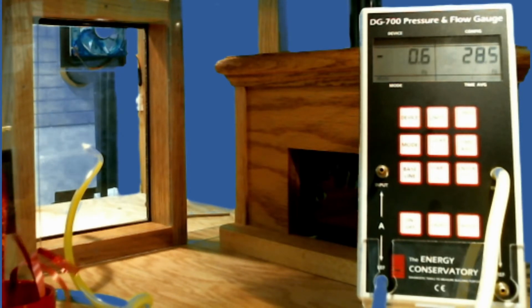So the number on the right there, that's the room pressure. Just like we had 50 something on the other one. This is not quite as bad, but it's still a pretty high number. But again, remember, we're in a little model house. I have seen numbers as high as 30 in a house that had a small bedroom, where that duct was configured close to the unit in the attic, and it just dumped a lot of air into that room.